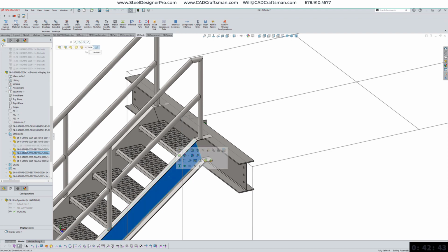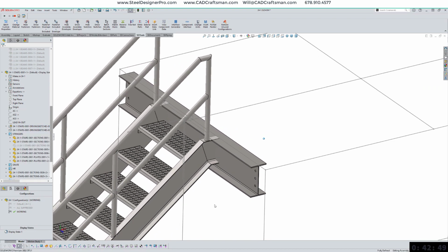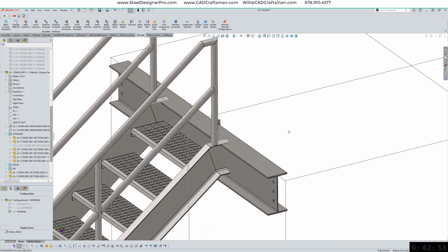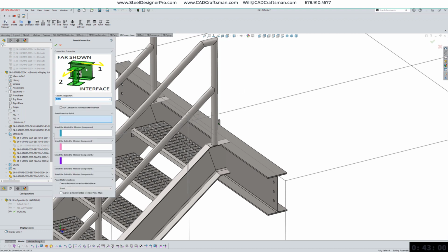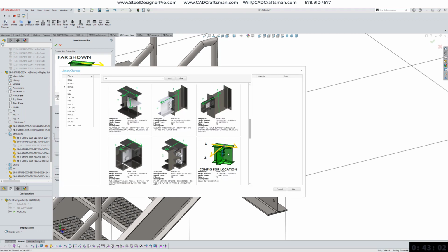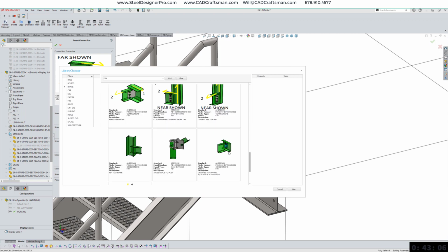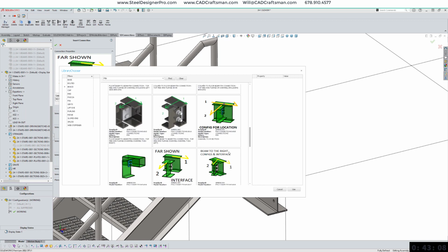I will show one of the stair driving sketches to provide location points for connections. We can now select the SD Connections tab and Fin button for the beam to channel connections. After inserting both connections, I verify the plate positions are as desired and change configurations as required.